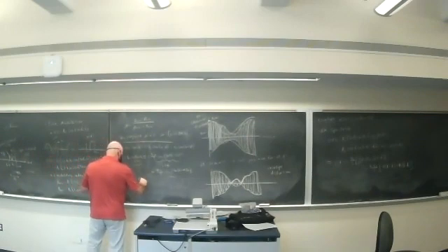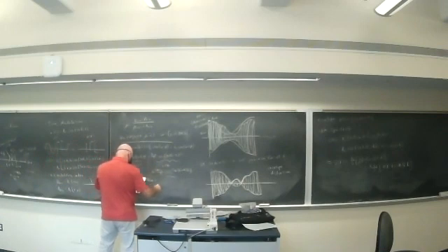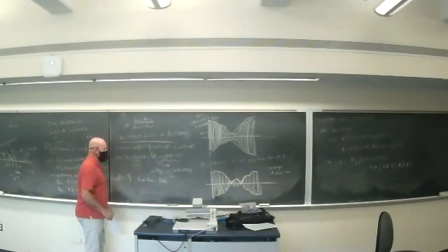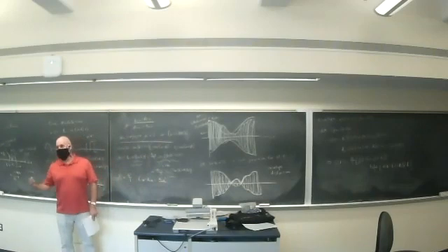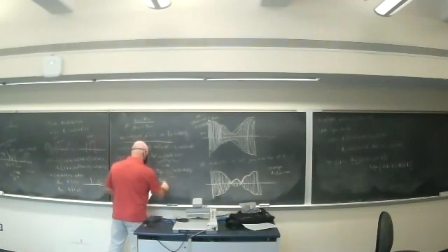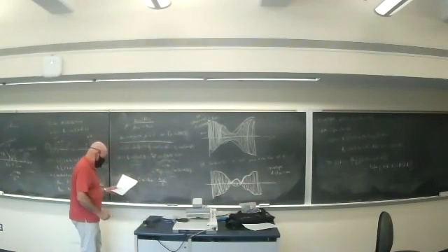And then the lower sideband and upper sideband have the same power. That's the power in this term. And that's going to be the amplitude squared, AC squared mu squared over, but here the amplitude has a 2 in it, so I square that and get 4, and then double it again because of the RMS, and so I get 8.